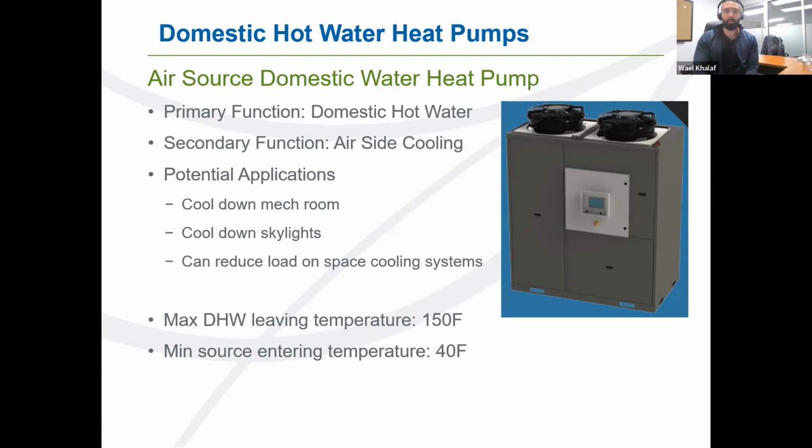I think it would be prudent to just do the analysis every time, in order to determine how much MBH I can get out of my domestic hot water, and how much domestic hot water storage I want to couple with that, in order to have the best solution possible for a particular application. So unfortunately, I wouldn't have a rule of thumb. I would just do the analysis every time.